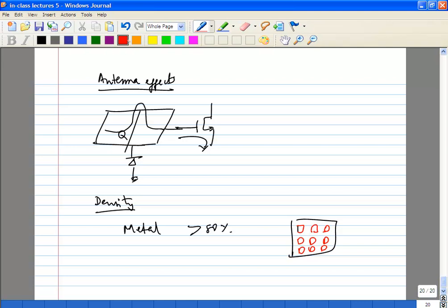So you will have to make sure. Typically for RF circuits, for the signal portion of the circuits, you definitely want to do what is called custom fill. So there are auto programs. Obviously it will find out what metal layer is available already there, and it won't fill on that metal layer, but it will fill on other metal layers. Okay, but you don't want to do that.